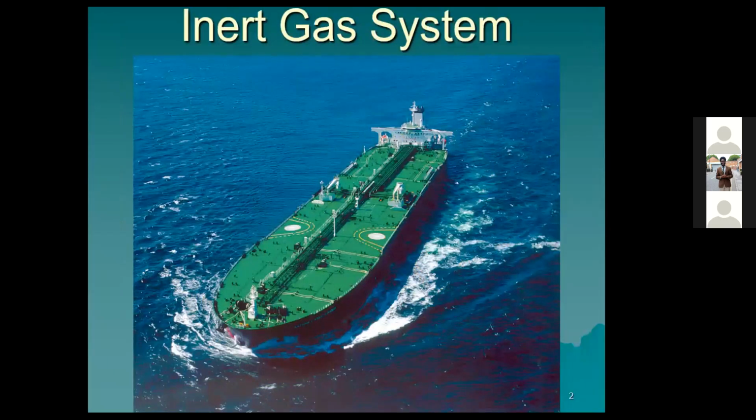So inert gas is applicable to only tankers. Historically, inert gas is like a flue gas. It doesn't support combustion. What it does is that it reduces the oxygen content to a level that cannot support combustion. So if you are transporting crude oil that has vapors,